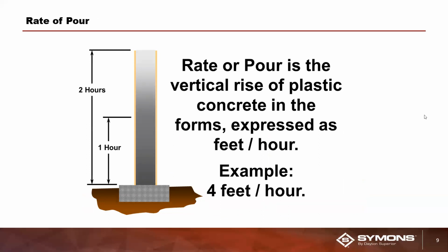What does vary the pressure is the rate of pour, how much concrete you're actually putting into the form. The rate of pour is the vertical rise of plastic concrete in the forms, expressed in feet per hour. How many feet of concrete you are putting in the form in 1 hour's time will give you what kind of pressure you're going to put on the form.